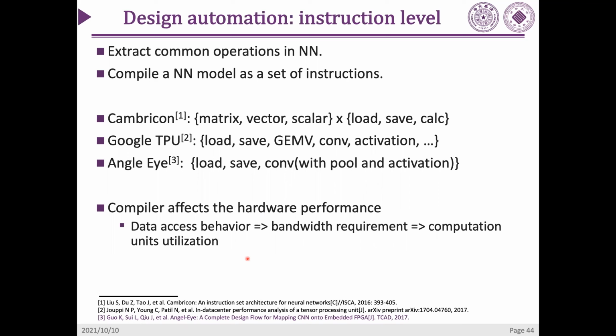It will decide the bandwidth requirement and also the computation unit utilization. So how to design your instructions and how to compile your neural network structure into the instructions is a very important problem when you design your own neural network accelerator.